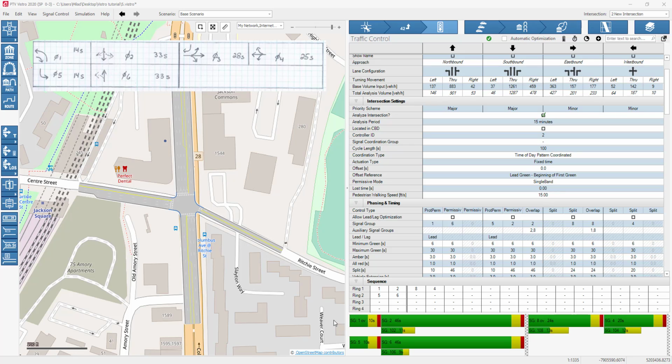If you compare the split's timing in the given diagram and the software diagram, you may understand they are not the same. For changing the diagram in the software, I click at the end of each split and hold it and move it.